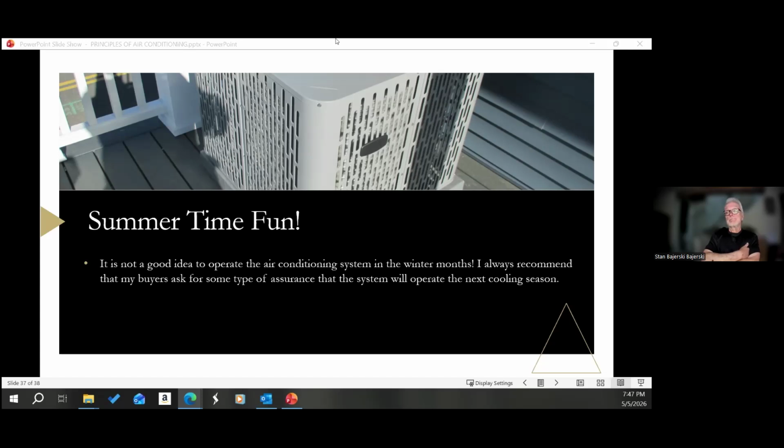Right. And the other thing too, on the R22, not to beat it to death, but I've gotten a number of phone calls where I put everything in the report. I've done my job. At the inspection, I'm explaining to them that because of the R22, you can't just put another refrigerant in there. So both the air handler and the condenser have to be replaced. But they're just not going to keep the air handler a lot of the time. Correct. And I'll get a call back and they'll say, listen, you did an inspection 3 years ago. It's R22. You said the outside unit just needed replaced, and they're telling me the inside unit has to be replaced.